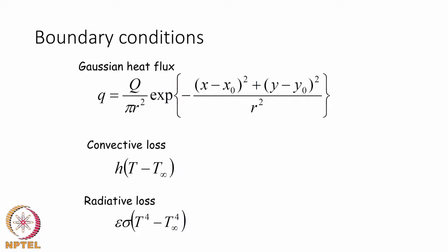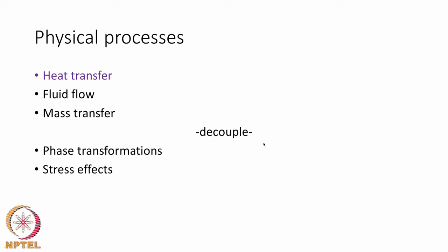Some of these may be extended with different terms on different sides of the material that is being joined or clad. So, it is important for us to ensure that these conditions are understood very well before we apply them to a situation in industry, and therefore, we are going to go in depth one after the other. So, in this particular lesson, we are going to look at the first aspect, namely the heat flux, to show that Gaussian, while being most popular, is also not adequate for many of the situations that we encounter in real life industrial scenarios.